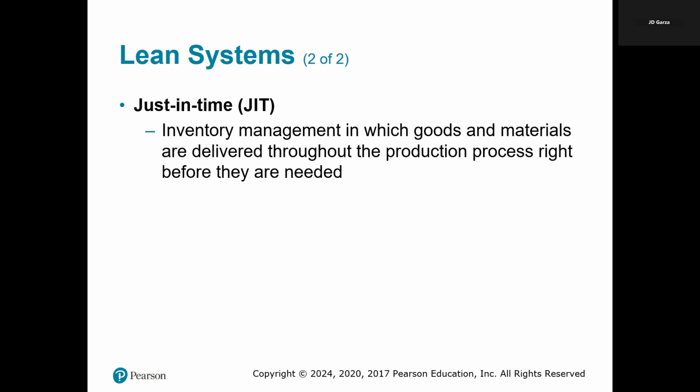So I just spoke about the Gantt chart a couple slides before. Sorry, about the just in time, okay? And this here, the just in time, a little more in depth, this is an inventory system. This is a key component of lean systems. It aims to enhance efficiency by ensuring that materials and goods are delivered exactly when they're needed in the production process, meaning that it minimizes waste and even inventory costs.